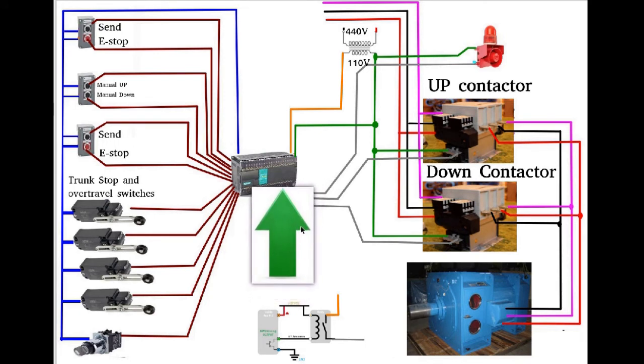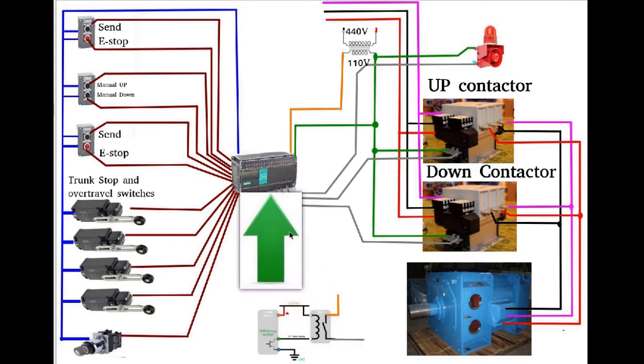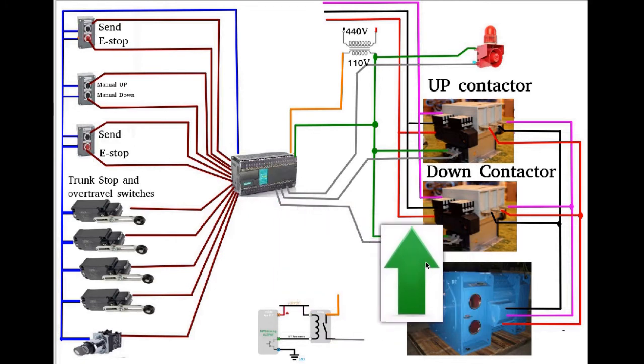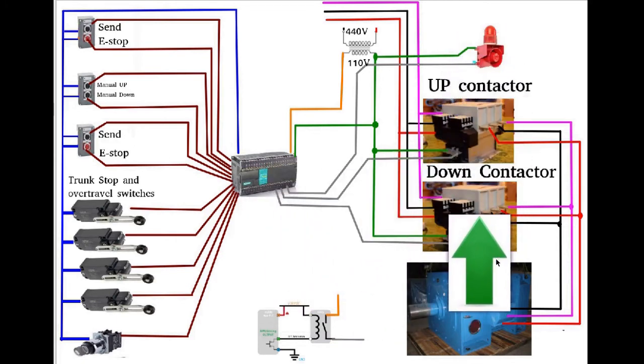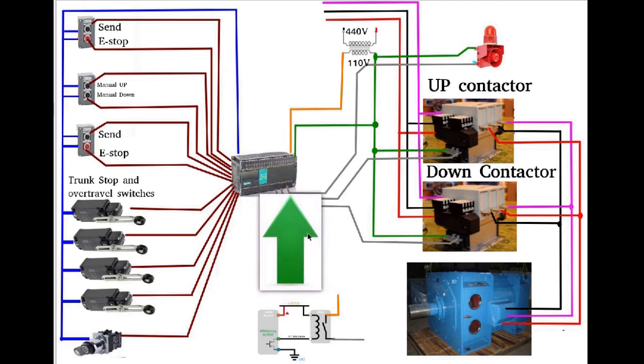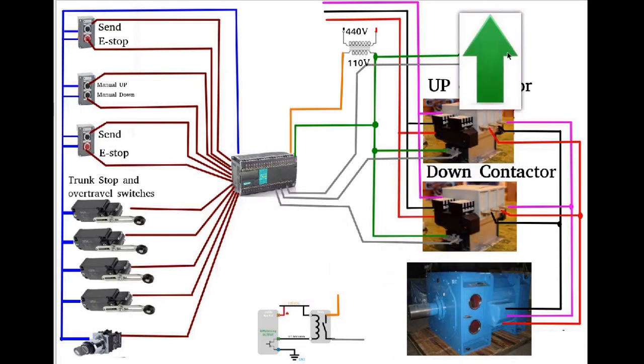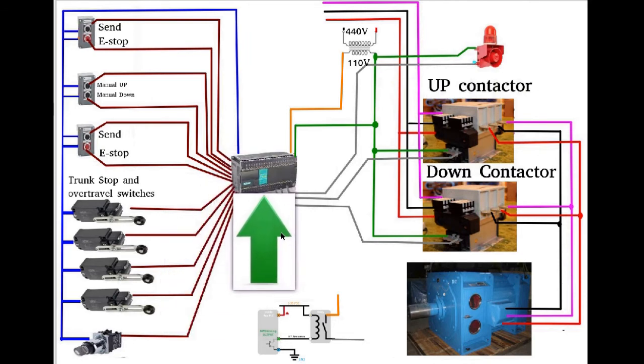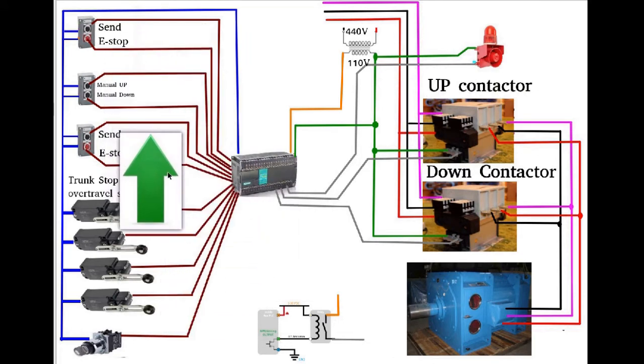Now, notice how it's wired inside, assuming that it's a relay. We got power coming in on this leg of power over here, and when it closes, it just transfers that side to this side over here, and that's how it gets power to the other leg to energize these things. The PLC decides when this load gets energized based on the instructions of the program and the inputs.